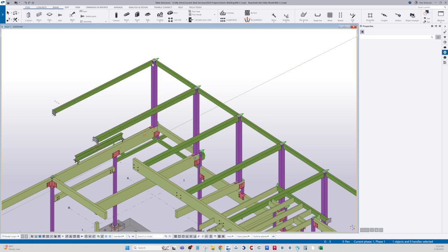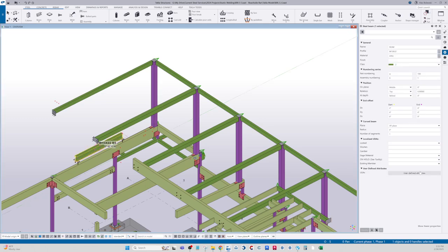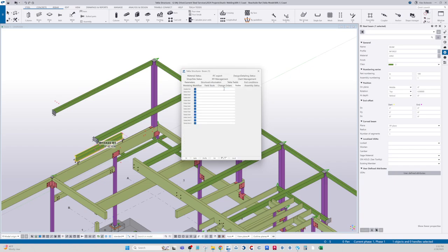on the actual beam. So like actually here, let's just do it real quick. That way you see it. So notes, line 1, nailer holes. Or here, top flange holes, right? Because your fabricator will know. Here, actually, nailer holes. Then there's no question. And click modify.